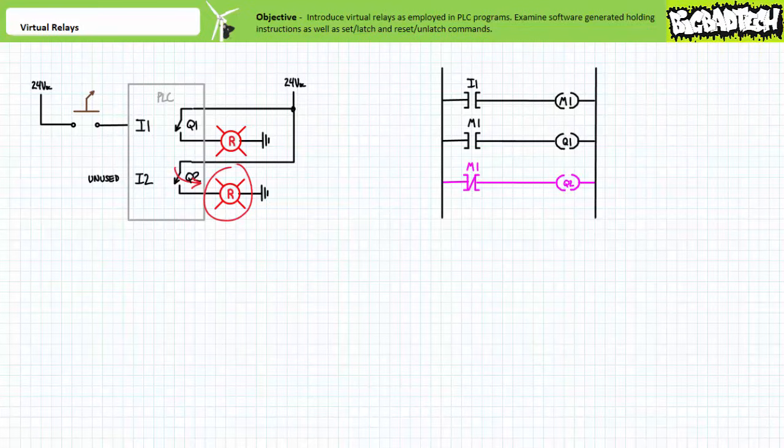If, however, the logic leading to the M1 coil does permit logical continuity, the M1 coil would be energized, and the PLC would assign a logical 1 to virtual relay M1. An operator does so by closing the normally open maintain contact selector switch on I1 to energize the coil of virtual relay M1. The make instruction examining input 1 permits logical continuity onto virtual relay M1.